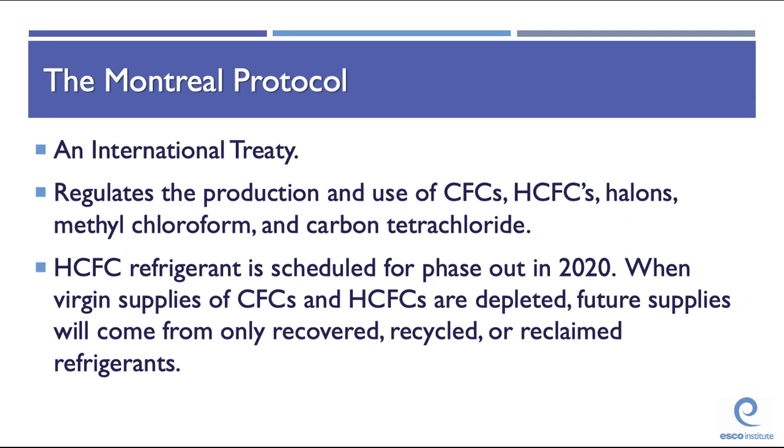In the United States, CFCs was the first substance group that was phased out of production. HCFC refrigerants are scheduled for phase-out in 2020, when virgin supplies of restricted refrigerant are depleted. Future supplies will come only from recovered, recycled, or reclaimed refrigerants.